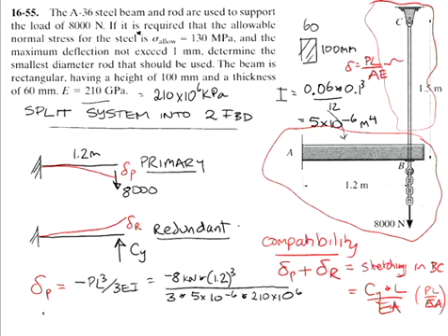Now when I look at my redundant deflection, sorry, I'm writing right above that so I can't write it out. Once again we want the deflection under the point load. But this time our point load is CY. So it's again PL on 3EI, but this time our P force is CY times your 1.2 to the power of 3. I'll just write it as 3EI here.